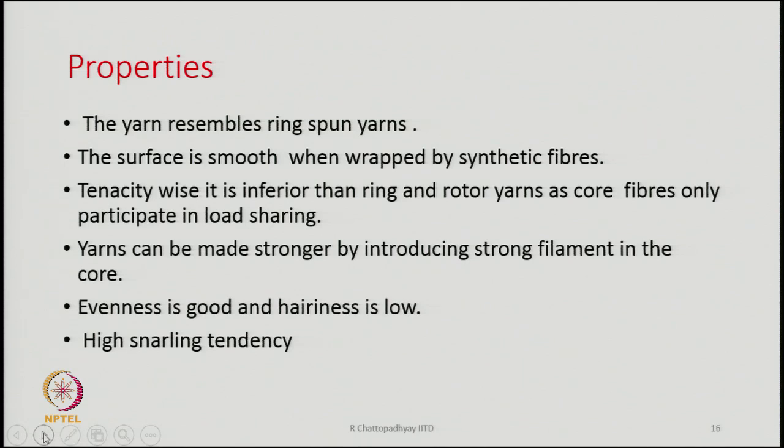In general properties, the yarn resembles ring spun yarn look wise. Surface is smooth when wrapped by synthetic fibers. Tenacity wise inferior than ring and rotor yarns. Yarn can be made stronger by introducing strong filament. We have to take the help of filament to make it strong.